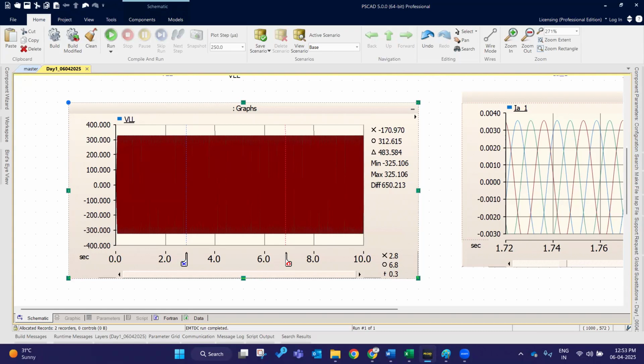Okay, changing winding, unable to run. This is bus 2, not possible. Enable instantaneous current. Run the simulation. These both are RMS plots. Yes, of course. Yes, yes, I haven't changed any parameters in the elements. I just copied and pasted here. But upon performing our simulation, we must change them.